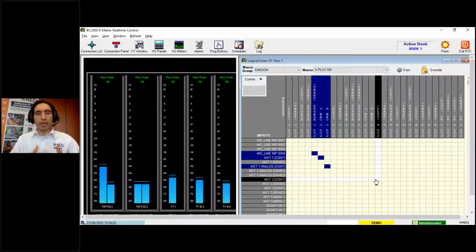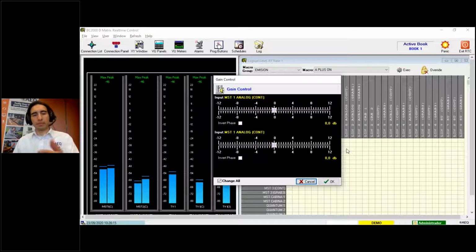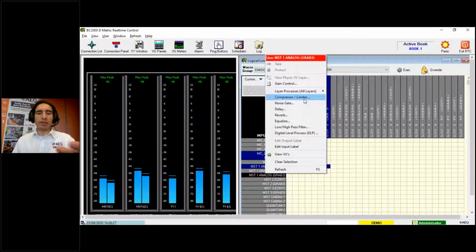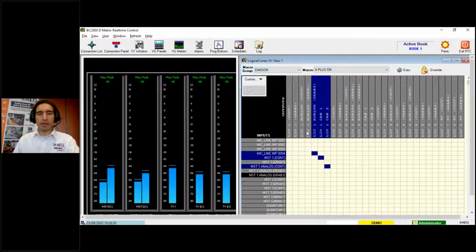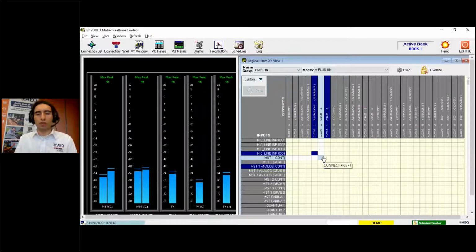outputs. Of course, we can send that audio over Dante to other interfaces, as I said, and then here we make the cross point. In the cross point, we can control maybe the level of the signals in the inputs, outputs, and cross points. Of course, we can group them like in stereo. We could have different processes, like maybe an equalization. And here we have different presets and control in real time the parameters of that equalization or other kind of process in that signal.